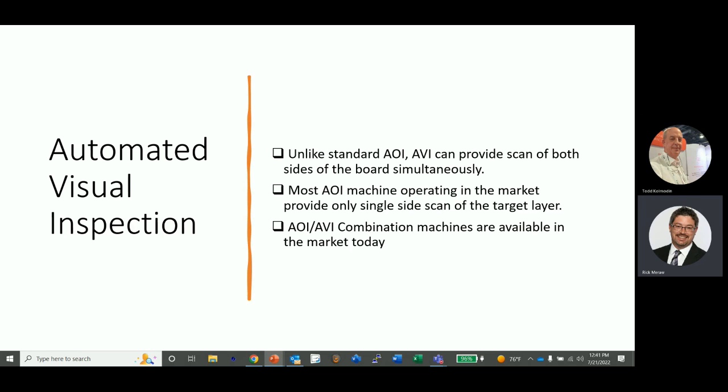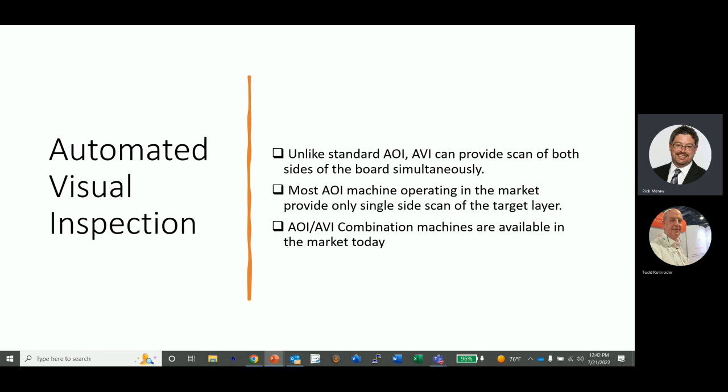Yes, that's correct, Todd. As I mentioned, it sees everything. Some of the fine inspection measurements cannot be done, but a lot of them, I'd say 80% of them, can be done using the AOI. The AOIs usually go through at some sort of speed, and sometimes the speed may vary the dimensional part a little bit, Todd.